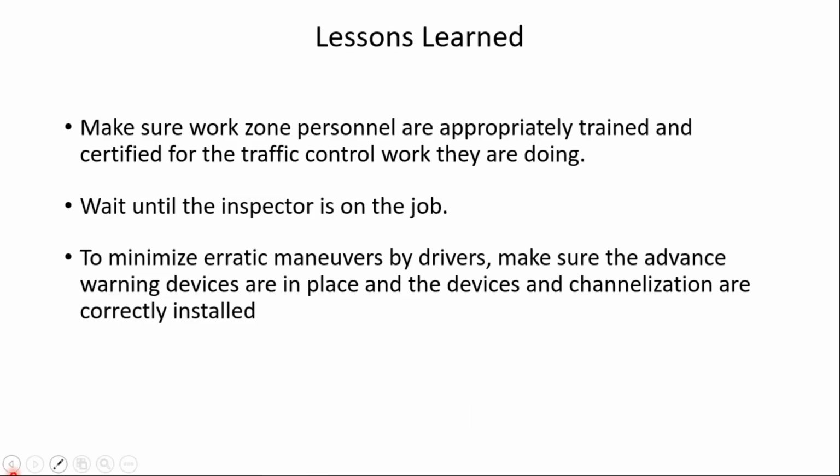The other thing that I haven't mentioned, but you saw that this happened about 8 in the morning. There was a state DOT inspector assigned to this job. He had just not arrived yet. He arrived shortly after the crash occurred. But my thinking is that the crew, especially since they had never installed a lane closure before they started work, really should have waited until the state inspector was on the job and could have given them some guidance.